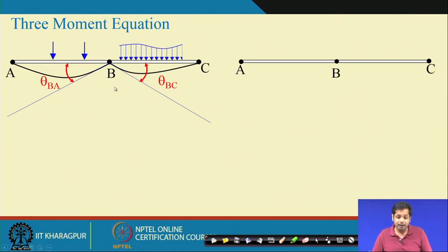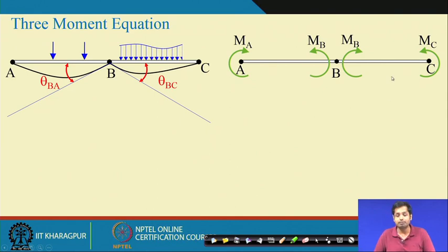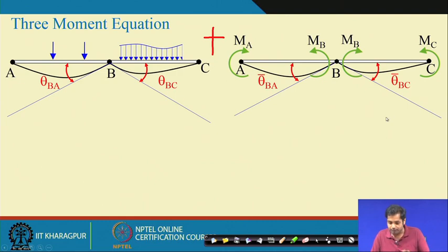Then we also need the basic determinate structure subjected to the redundant forces. The redundant forces are the moments here. So, this is the basic determinate structure subjected to redundant force, and then the linear superposition theory says the solution of the actual structure should be equal to the solution of these two, this plus this. That is what we did in the method of consistent deformation. Compatibility between this deformation and this deformation needs to be maintained, and that compatibility gives us the additional equation. The deformed shape of this is, suppose, this, and theta bar represents the rotation at B due to the redundant force.